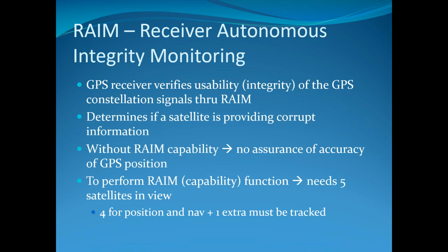So just so you guys know, RAIM is not an individual type of satellite navigation, okay? But RAIM is a system that monitors the amount of satellite signal in a given area at a given time. So if we are going to use GPS or RNAV or the GNSS, any of these satellite navigation systems, we have to do what's called a RAIM check for our intended route of flight.